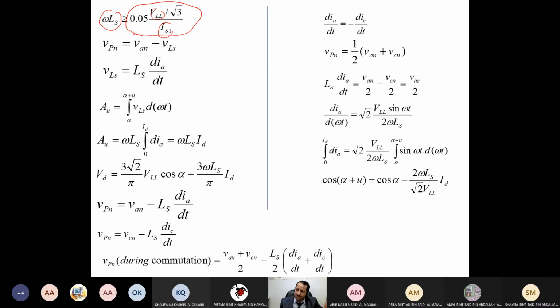When we say supply inductance, we are not talking about a separate component. The supply is either a generator or a transformer. Both of them have windings, and both of them have inductance. We cannot design your supply regardless of the inductance, whatever it will be, because at the end this inductance will cause a short circuit during commutation. Short circuit is not a good phenomenon unless it's used for an application, for example welding. Otherwise, it affects the supply, the load, and the equipment in between.